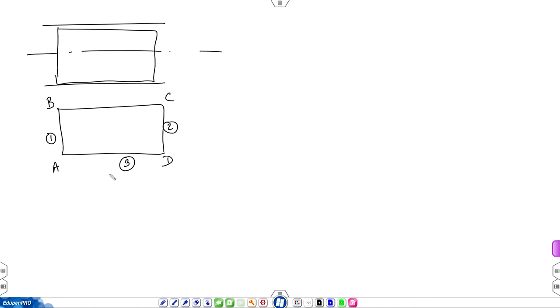Choose surface 3 to coincide with the wall, so that u dot n is 0. It will simplify your integrals. This flow coming in, flow going out. Okay. This is CV, this is CS.